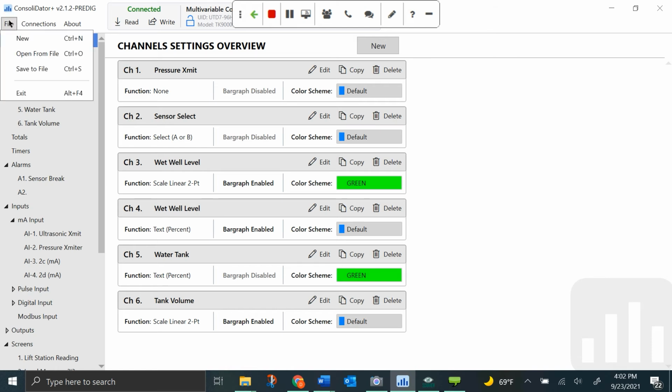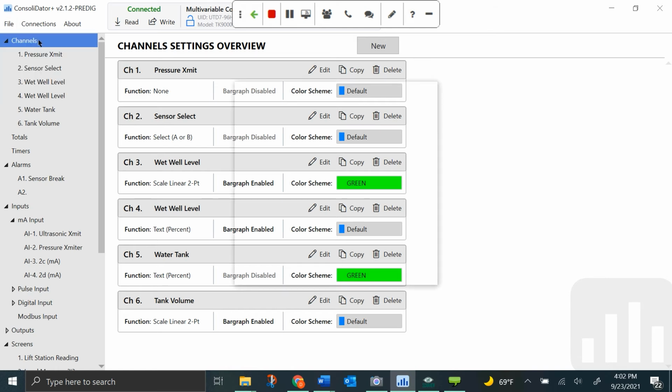We come up to this file button here, we press new, and then we have slots 1 through 7. This is a demo that I'm connecting this to, so I just know off the top of my head which inputs I have. For example, in slot 1, I have pulse inputs. In slot 2, I have milliamp inputs, and then I skip a slot, and I have milliamp outputs. I skip a slot, and I have relay outputs. Now, this might be different if you have a consolidator that has nothing but 28 analog inputs; all 7 of those slots are going to have milliamp inputs. So it's very dependent on the device to which it's connected.